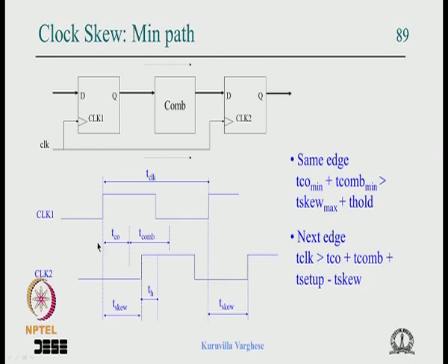So in essence, when somebody is routing the clock in a chip, if there is a relative delay between the endpoints, wherever it is, that is troublesome. That can reduce the clock frequency and can create hold time violations. So there needs to be a mechanism to route the clock tree such that the relative delays between the endpoints are minimal.